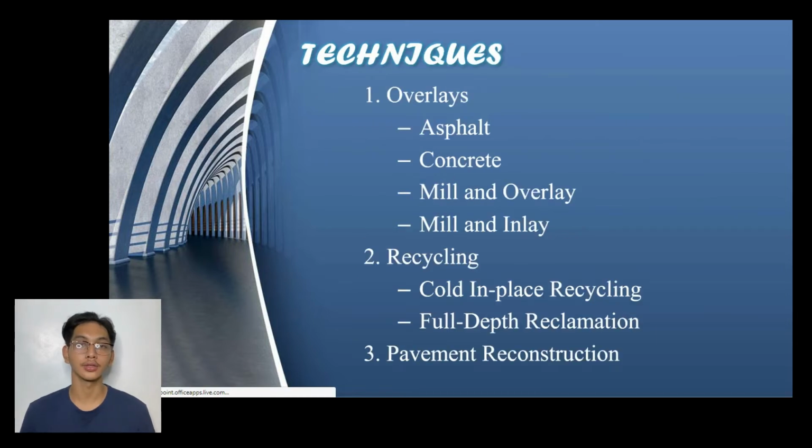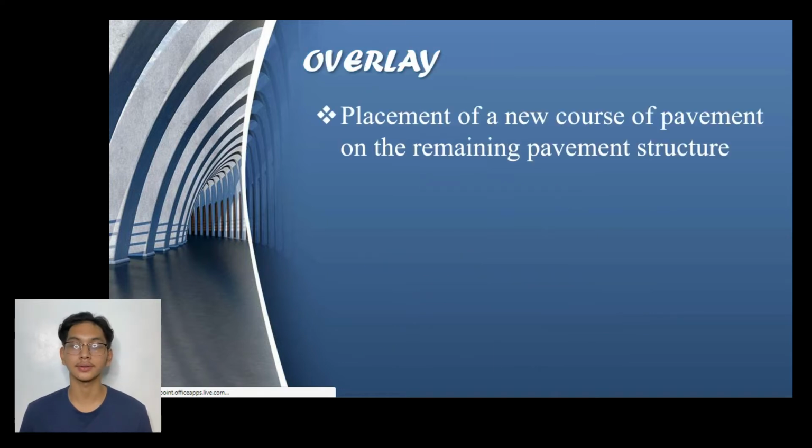Pavement rehabilitation also has different techniques. One of these is the overlays, which includes asphalt, concrete, mill and overlay, mill and inlay. The second technique is recycling. First way of this is the cold in-place recycling, and another way is full depth reclamation. The third technique is the pavement reconstruction. Now let's talk about it one by one.